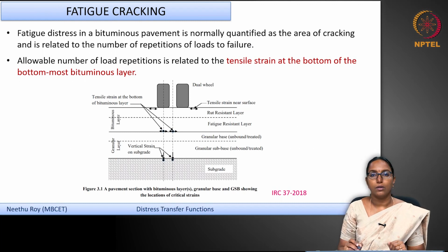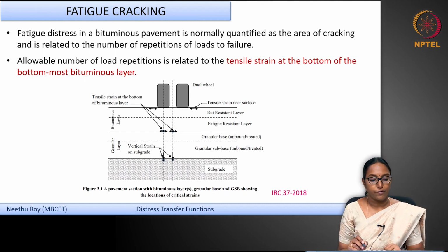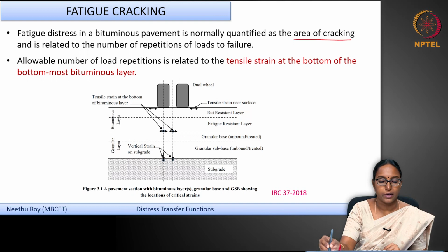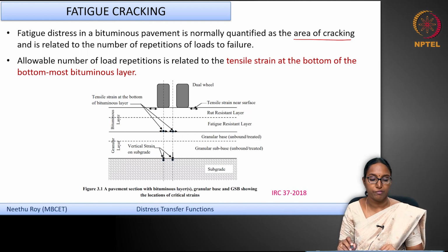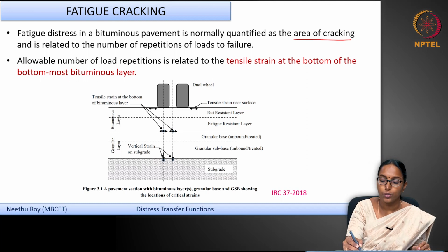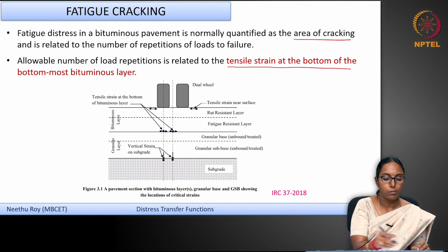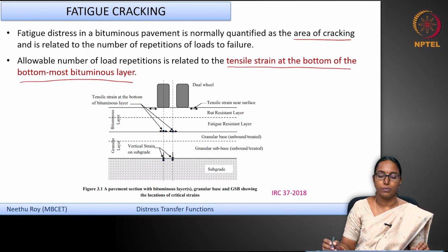Now, in order to consider this fatigue cracking for design, the fatigue distress is quantified in terms of the area of cracking that you see on the surface, and this is related to the number of repetitions of loads to failure, okay. Now, that number of load repetitions is actually related to the tensile strain at the bottom of the bottommost bituminous layer.